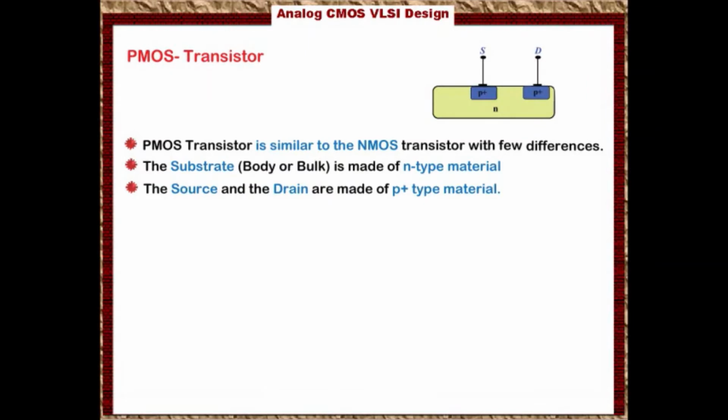So we can state that as in the NMOS there is a silicon dioxide layer and a poly layer at the gate. In fact, for the CMOS technology, because both NMOS and PMOS are built on the same wafer, we have the same layer of polysilicon and the silicon dioxide for both transistors.